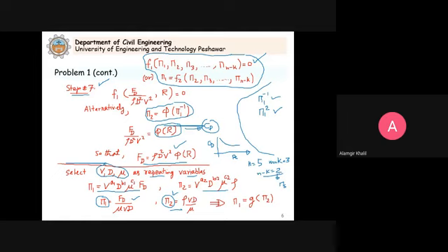In solving this problem, the number of pi groups will not change. You cannot say that if somebody else solves this problem, he or she may have 3 pi's. This is not possible. You solve it with 2 pi groups, and somebody else will still solve it with 2 pi groups, because this is coming from the Buckingham pi theorem, and that cannot be different.